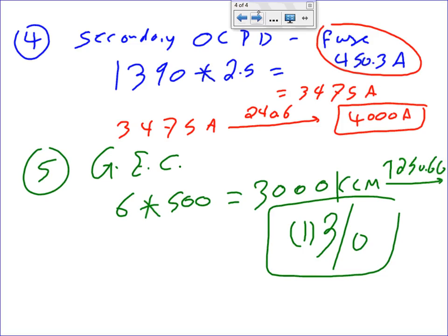Main bonding jumper, out the door. Why? Because the system is an ungrounded system. So I'm going to write a little note here just to remind you guys. Actually, this would be a main bonding jumper. It could be called something else depending on how you use the transformer. In this case, it's most likely a main bonding jumper because this is a service coming to my building. If I own the transformer from both sides, the high and the low, it becomes a system bonding jumper. Two names for the same thing. No main bonding jumper.